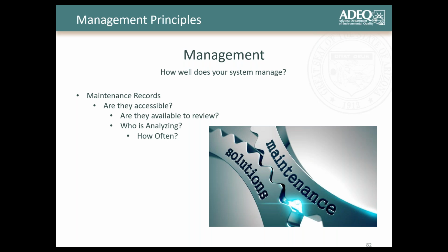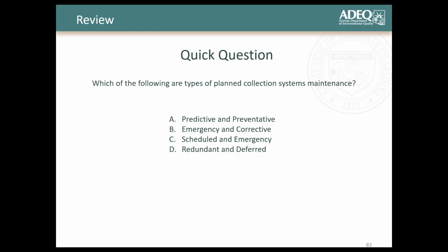So, how often are we analyzing our maintenance records? Things like your line cleaning data sheets or your CCTV inspections, all those things matter. How often you're having to do maintenance on a certain pump matters as far as decision making on overall management of your system, whether a pump needs to get replaced, rehabbed, or rebuilt.